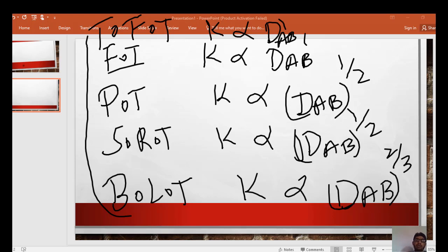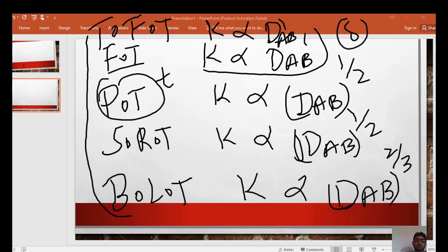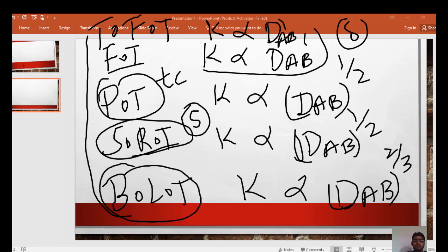The main parameter in the film theory and two film theory is the thickness of the film. Similarly, the main parameter in the penetration theory is the contact time. The main parameter in the surface renewal theory is S, the fractional surface area removed per unit time. The main parameter in this theory is the thickness of the layer, whether it is the boundary layer, concentration layer, or thermal layer, and the ratio of these layers gives us the Schmidt number.